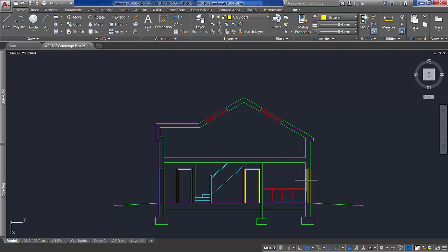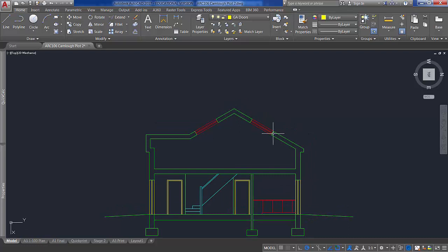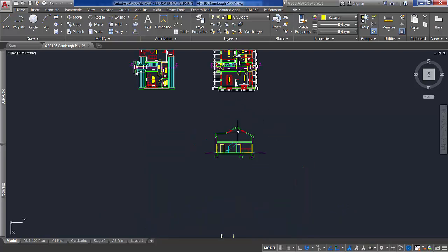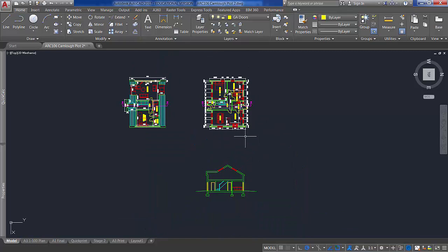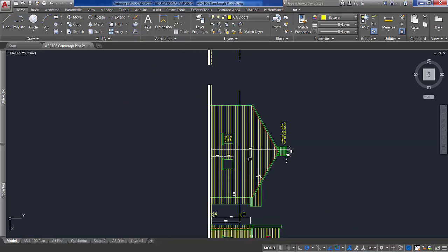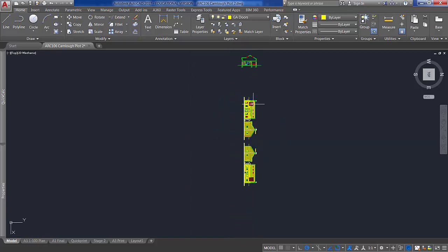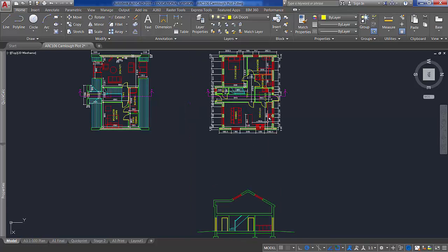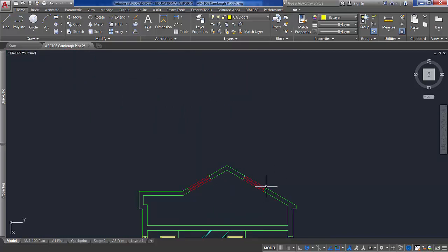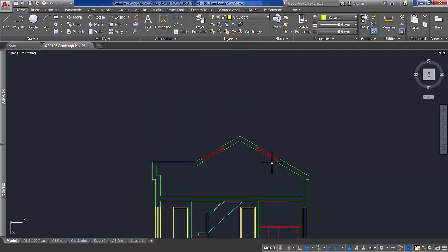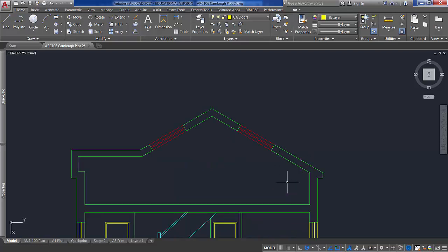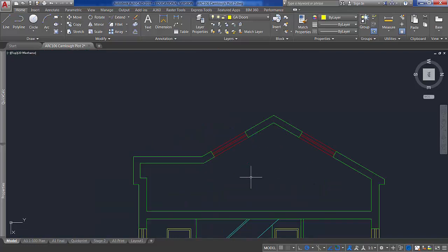Now what I've also done is added in the door at the front and back of the dwelling, and also the roof lights. And to get the exact location of those, what you would need to do is refer to the elevations and also the plan. Ultimately, the section is sometimes the best way to work out exactly where those ought to be though. So if you're working off specific heights, etc., especially if it's a lower window, maybe for a fire escape purpose or something like that, you will be looking at the building regulations and putting that in an exact position.